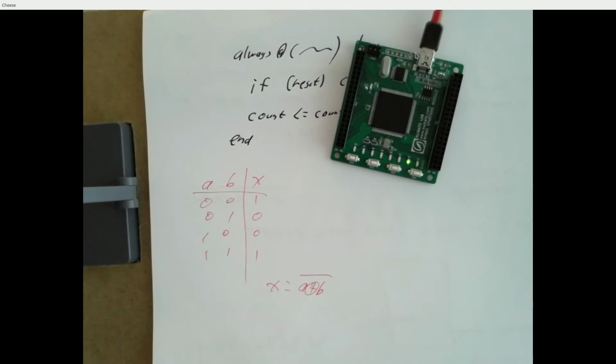In 270, we'll talk about ways you can do things like control the brightness of an LED, though, by making it blink. Because in some cases, we can turn it on for a millisecond, and then turn it off for a millisecond. Turn it on, turn it off. And you may not see it blinking, but your eye and brain will detect that it's half as bright as usual, because it's basically putting off half the energy. And if you turn it on for a millisecond and then turn it off for 2, and on for 1 and off for 2, it'll be about a third as bright.